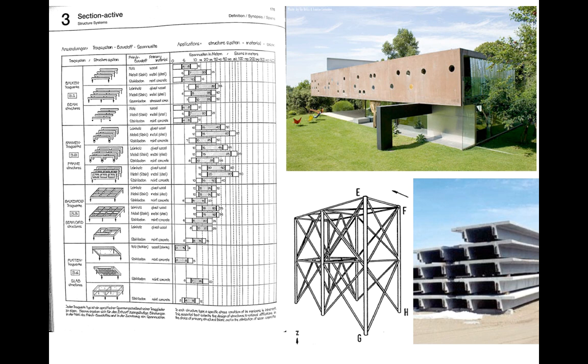We can stack beams and girders and slabs on top of each other 8, 9, 10 times without worrying too much about the height that the structural element itself actually takes. Right? We don't build multi-story buildings out of domes, because a dome relies on the height of its section to carry the load. So right away we lose all sorts of headroom if we think about trying to build a multi-story building out of domes.